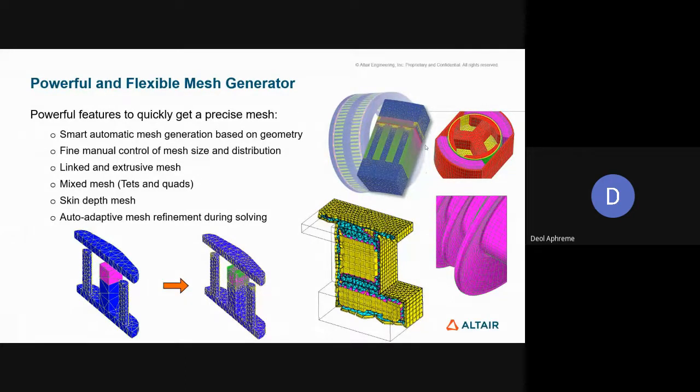So for example, the air gap of a stator and a rotor is where maximum energy conversion happens. So your electromagnetic energy is being converted into mechanical energy, which is a very high amount of flow, and a very high amount of changes occur in a very small region. So it is very important to mesh these regions very finely, and the rest of the regions, the stator core or the rotor core or the transformer's core, very few changes occur, and generalized changes can be visualized. So it's very important your mesh is appropriate to your project.